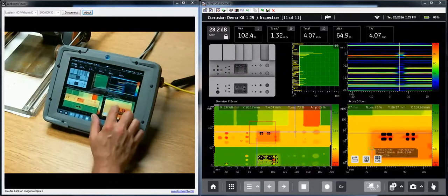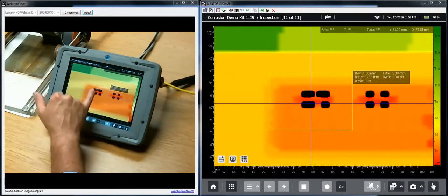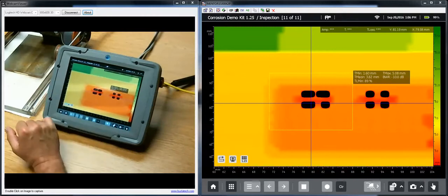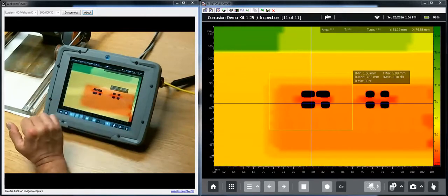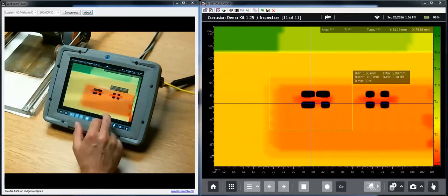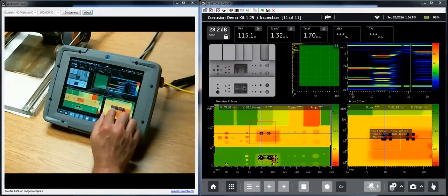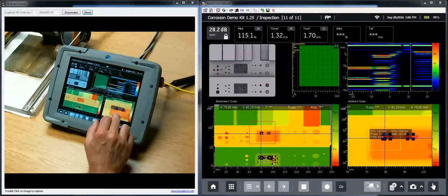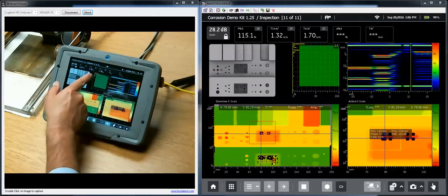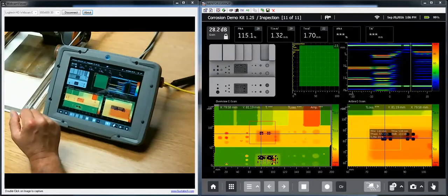I come in here in overview, I take a close look, and you'll notice I have a couple of black spots now on my C-scan, and that indicates to me that I've got some missing data there. Okay, so why am I missing data? Well, if I look very closely, where I have the crosshair placed in the middle of one of those black areas of the C-scan, when I look up here at my A-scan, I notice, well, shoot, my signal isn't quite breaking the gate.